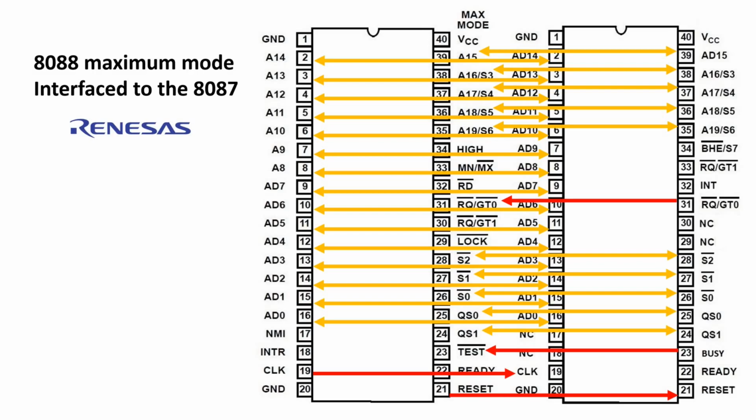Now it's interesting to understand how that works, because if the 8088 executes a floating point instruction, effectively the 8087 takes over and needs control of the bus to fetch the operands, as I understand it. It then crunches the numbers and it raises a busy flag while it's crunching the numbers. When busy goes low, the computation is complete.